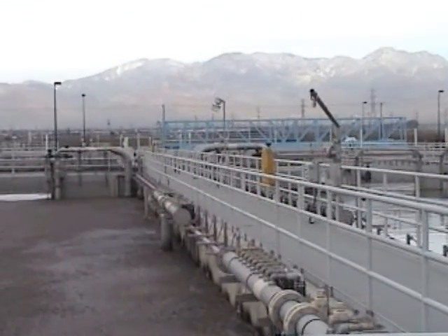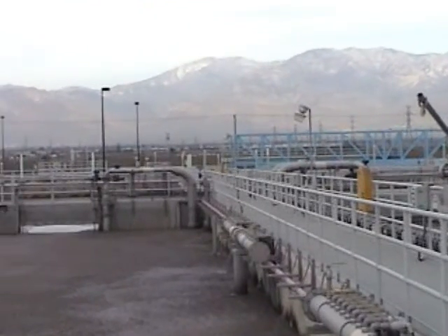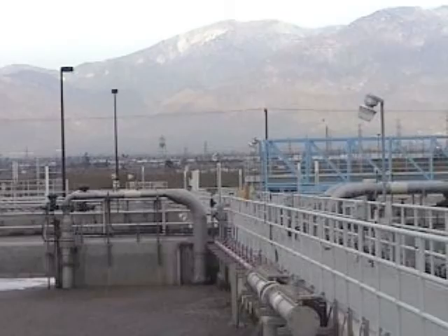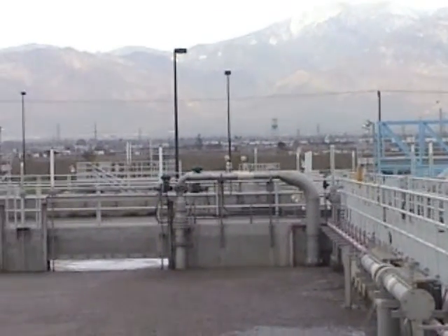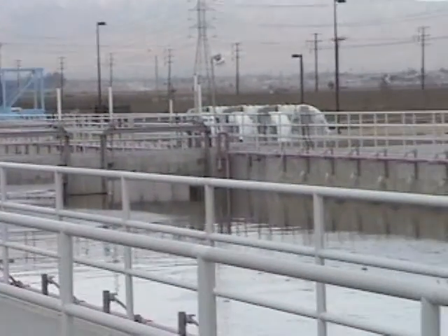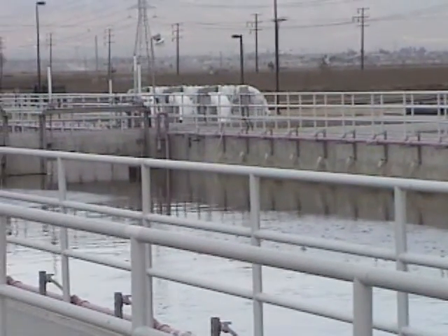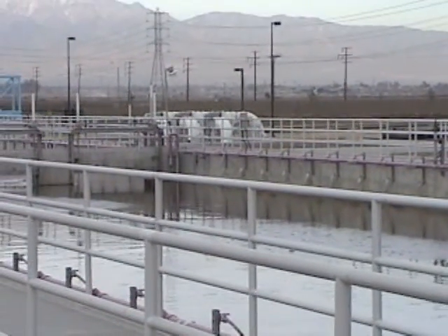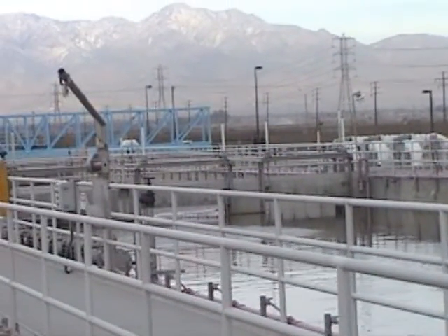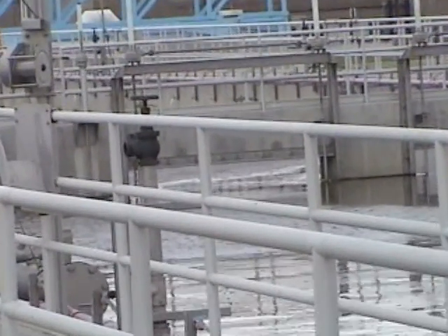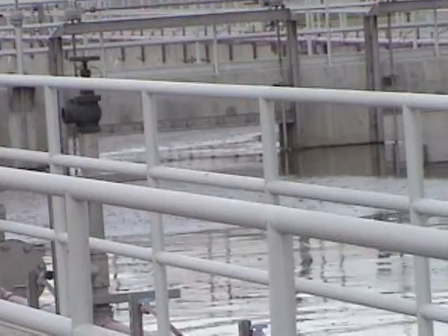When the valves are 100% open, it's telling you that the blower is pushing out as much air as it can and that it can't meet the DO set point. These blowers are enormous, and they can produce that kind of air, unless we have put in a command or a set point that will force them not to do that.